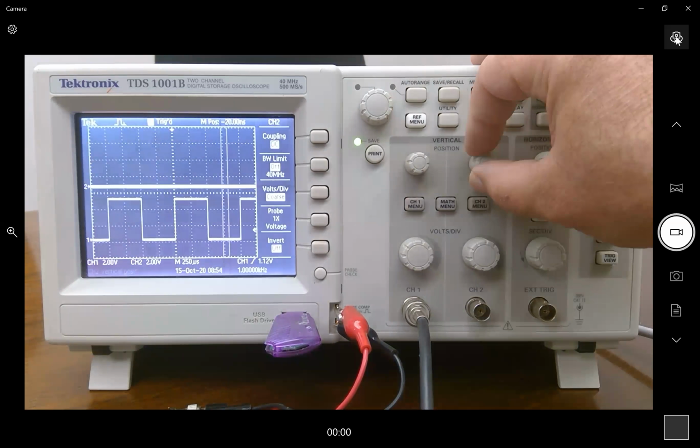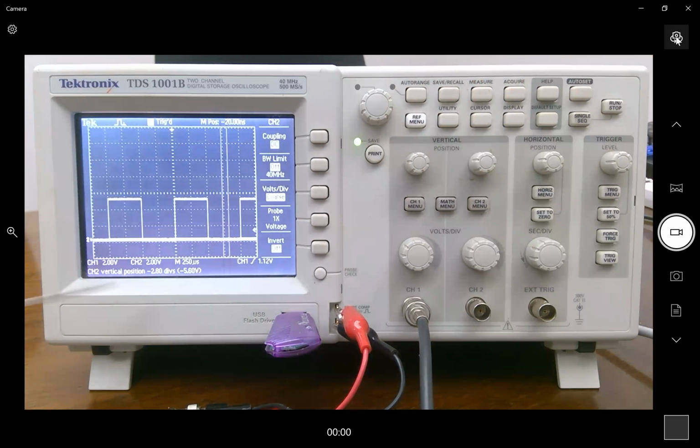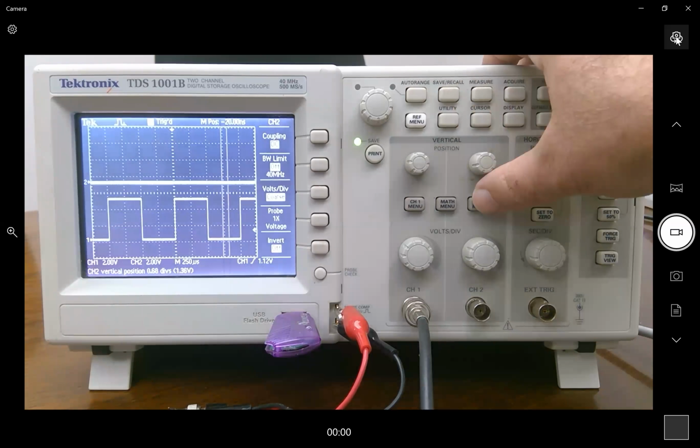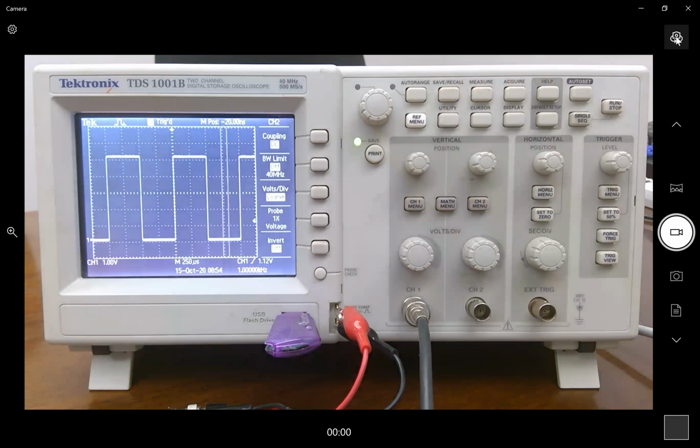Or I could take channel 2, match it up with channel 1, and if I want to do a comparison, like a crossover, say like a comparator would do, and you want to see when channel 2 is triggered compared to channel 1, you could lay them on each other. Some of the scopes are multicolored, which is an advantage, because here it's hard to discriminate between these two since they have the same color. But I'll get rid of channel 2 and we'll take channel 1 back up.